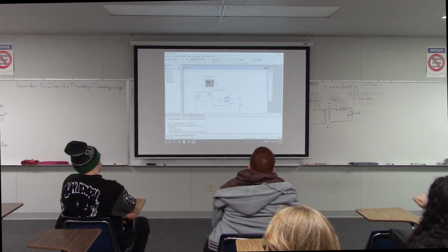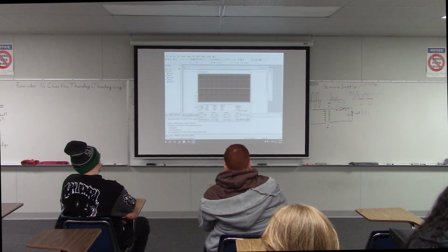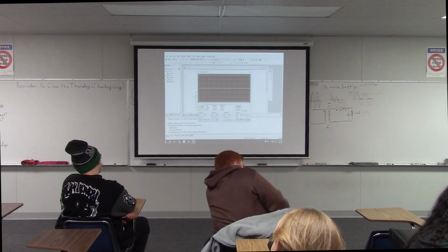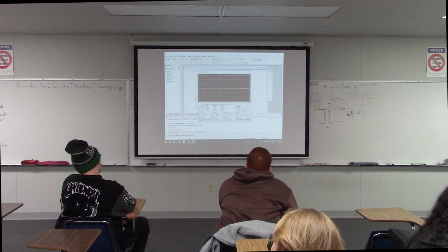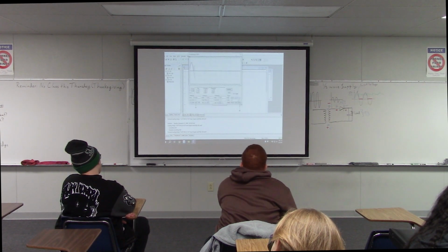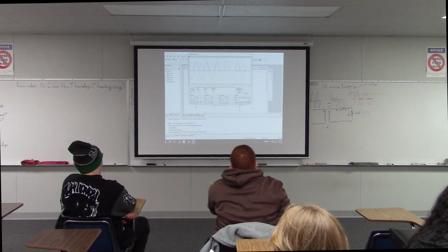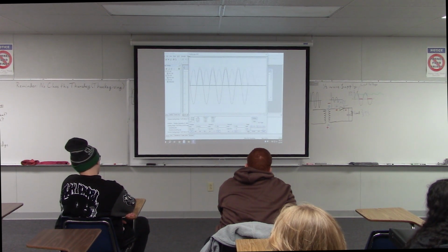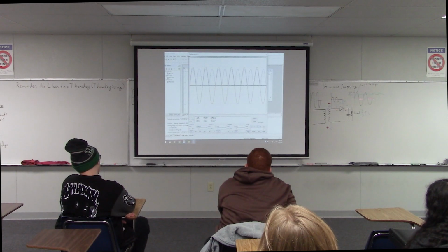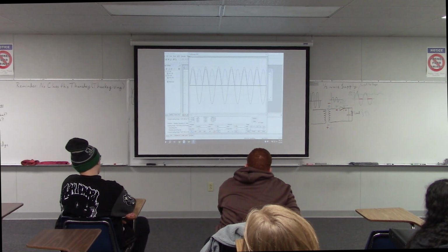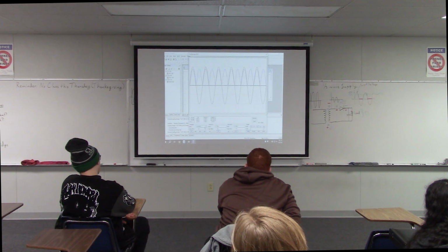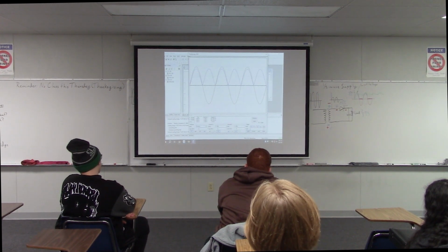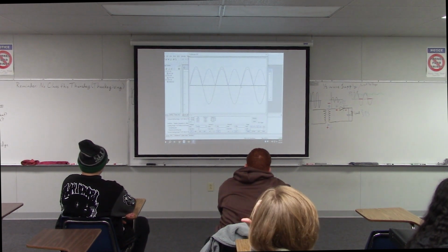Again, we run the simulation, we can open up the oscilloscope, and then we'd make these adjustments in order to see a nice signal. The adjustments that I make, personally: I reverse the color so that it's easier to see. I can make the window bigger. I turn on the triggering. I make it single triggering. And then I can adjust the time scale in order to zoom in a little bit in the horizontal direction, again keeping at least 2 complete cycles of the incoming wave there.